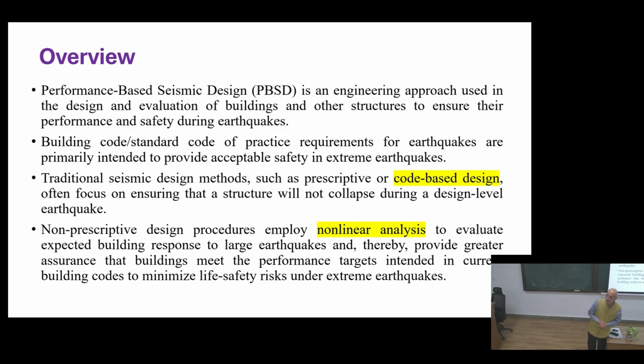When we use a non-prescriptive approach, because most of the code provisions mean the elastic design procedure is adopted. Elastic design, I will show some slides on it later as well, means that the force deformation curve is a straight line.